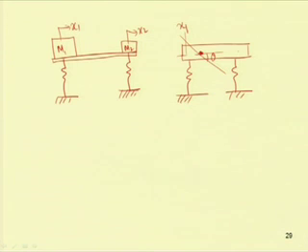Either one can represent by only translational displacement at these two ends or by using one translational and one rotation. Also, these points can be changed and one can get different types of equation. So, depending upon the chosen coordinate system, one can obtain a coupled or uncoupled equation of motion.